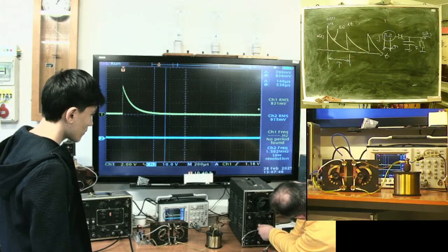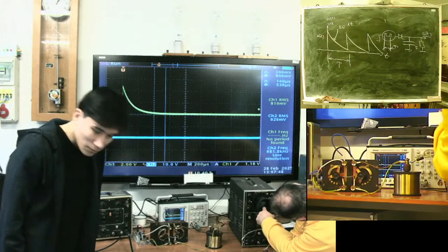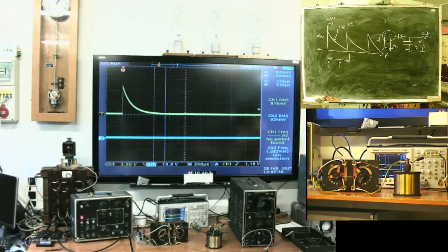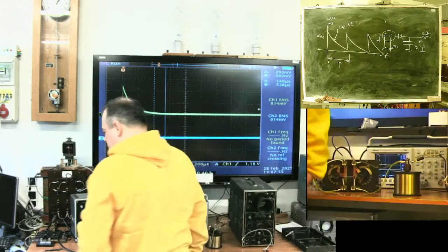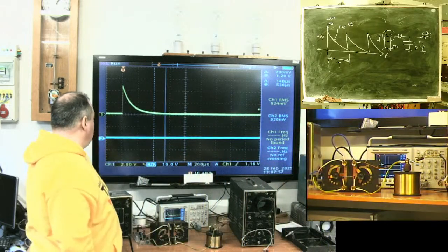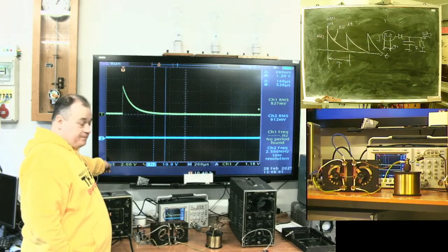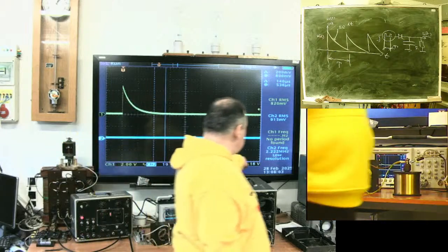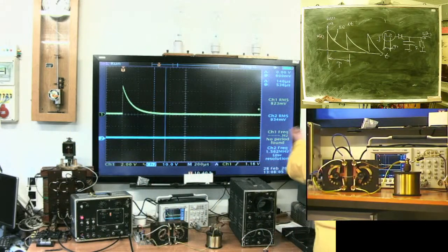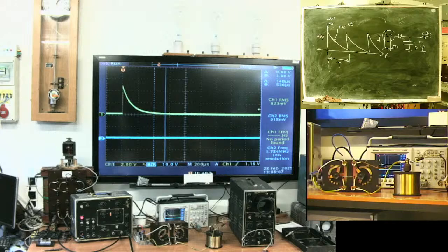1, 2, 3, 4 within. What's going on? For my scope, time begins here. It's a zero time. And at this point, memory ends. It's a digital scope. It shows what's inside the memory. For my scope, the end of time is at this line.